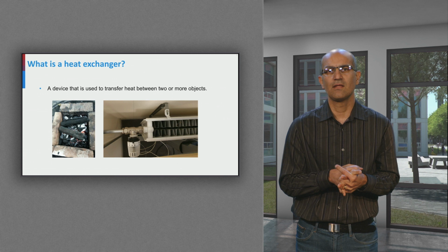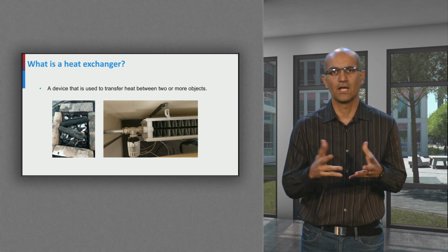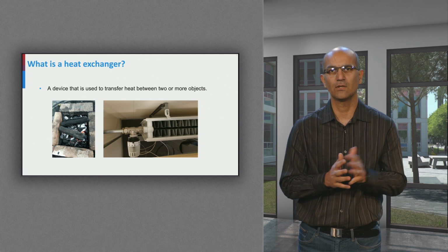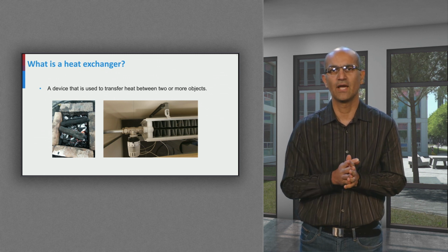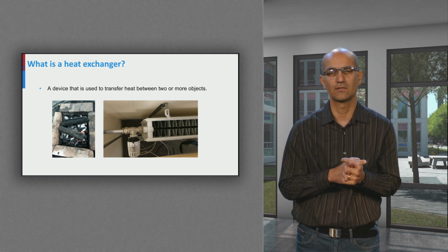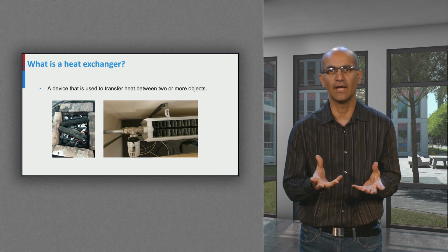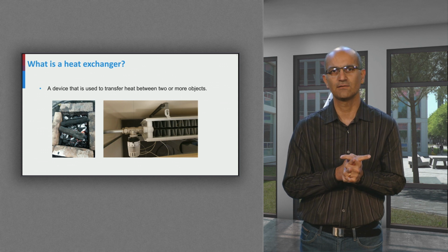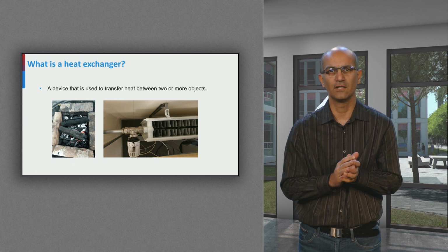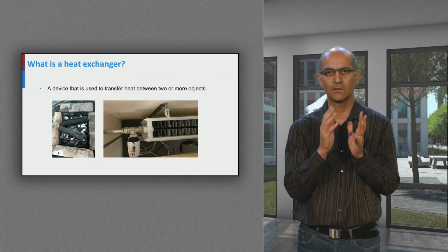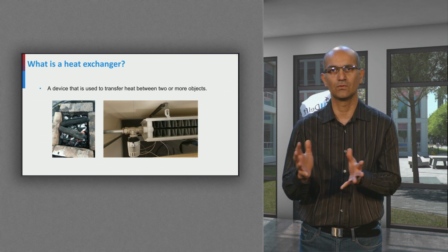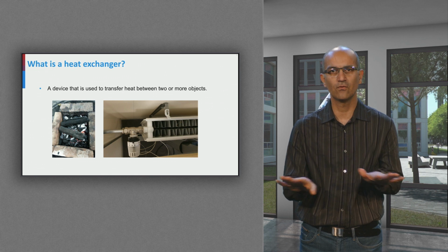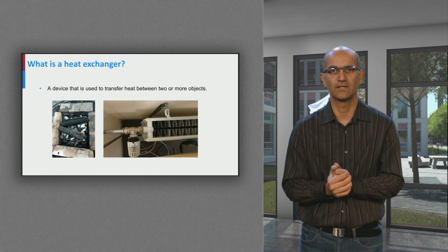Let's begin with what a heat exchanger is. Here I've got two photos, one of them taken from my charcoal barbecue at home and the other one from a water to air heat exchanger in my office. In both of them, heat is transferred to air. With the radiator, however, we would notice a control valve that regulates the hot water flow rate. If we fully open the valve, we expect the maximum heat transfer from hot water to air around the heater. And of course, if we shut the valve off, there would be no flow of water and no heat transfer.